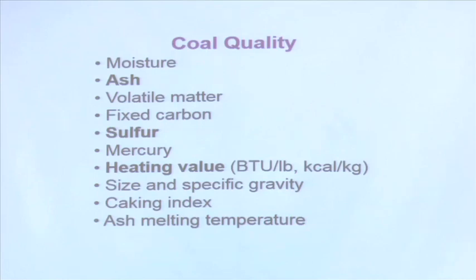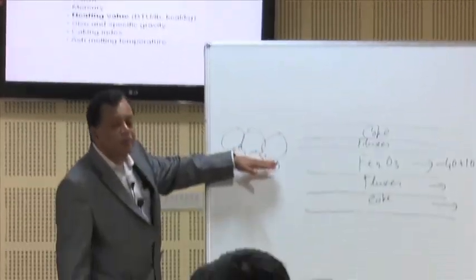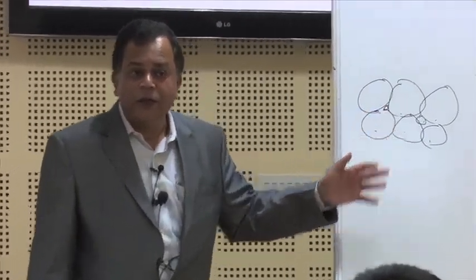But another kind of moisture matters for making my coal suitable for a power grid. After mining we use water as a medium fluid. So, we will have some surface moisture. The nature could be moisture adhered to the surfaces of the particles. The moisture could also come from entrapment between different particles. Like here, if I have different coals of different sizes, the moisture could be entrapped in that. So, you will have surface moistures.